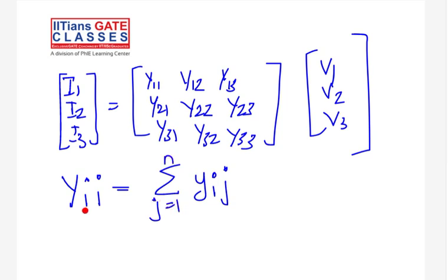So basically you see which all lines are connected or what all elements are connected to that node, find out their admittances and take the sum of it. That is your Yii, the diagonal elements, right? And capital Yij will be equal to minus yij.